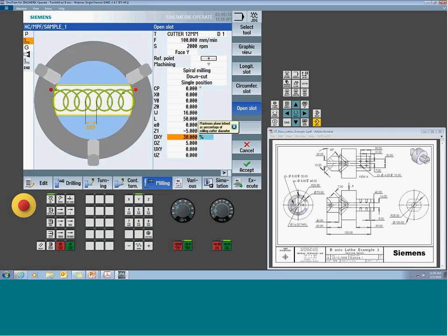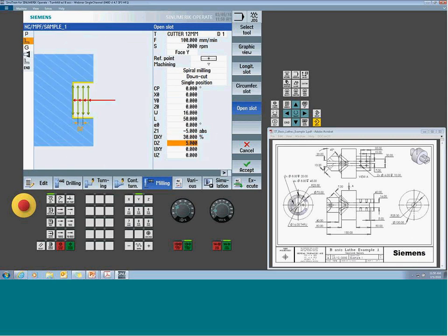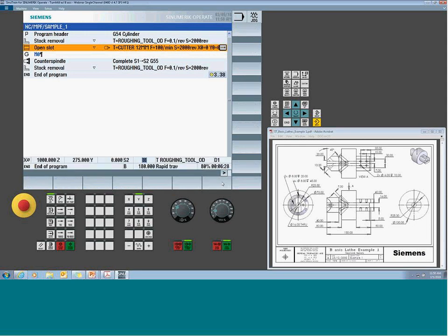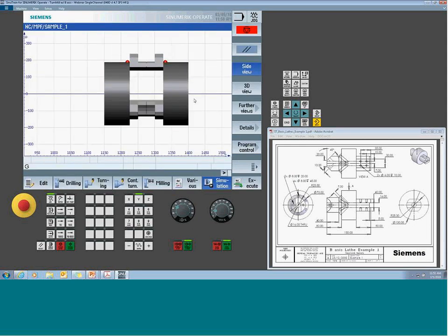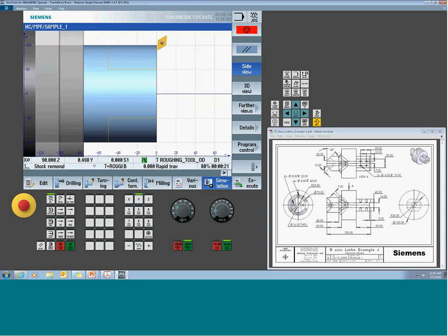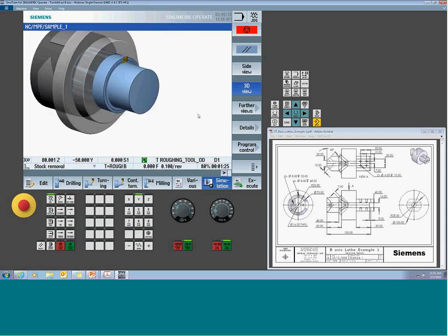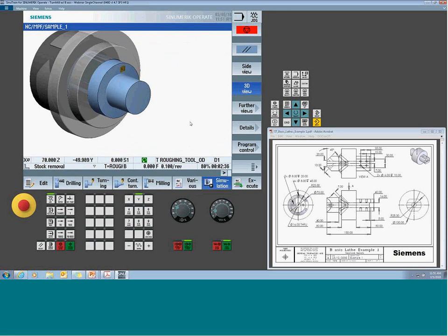Depth. This radial engagement, my barrel step over, I'm doing a 30% cutter diameter engagement. Depth pass. So again, this one just takes all in one cut. Leave material for a finished cut. Simulate it. We're now going to see the first turn feature, and we're going to see the machine slot come into play. Now I'm going to look at 3D here, give a little bit of rotation.